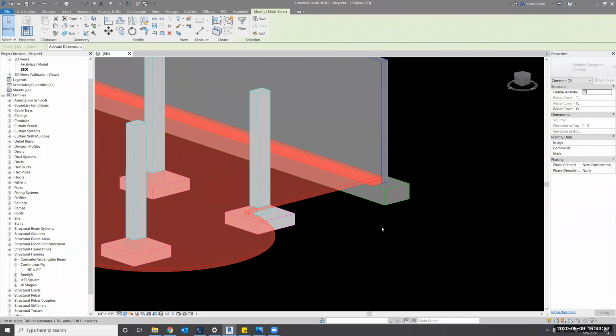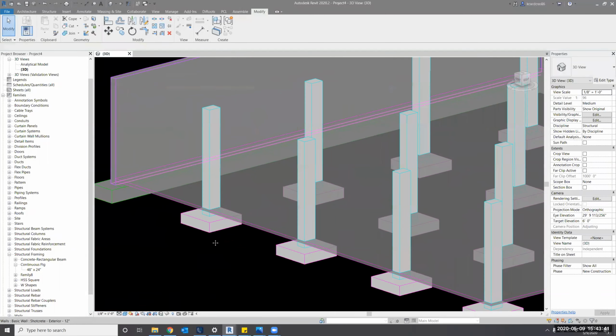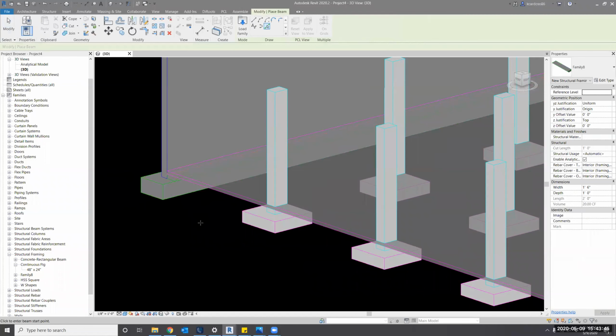All right. And you can see the power of using beams for foundations, because the beam tool has all these arcs and options for it, and this 3D snapping saves you a lot of time as opposed to modeling in a 2D view like a level 1, okay?